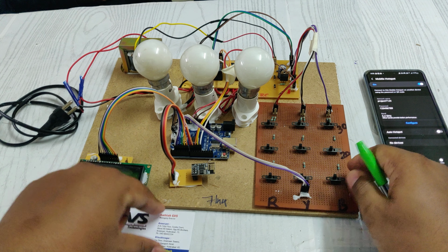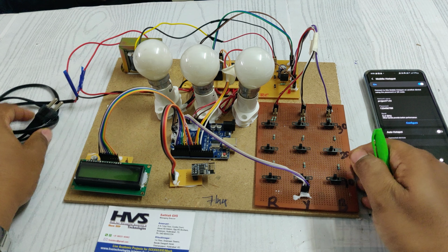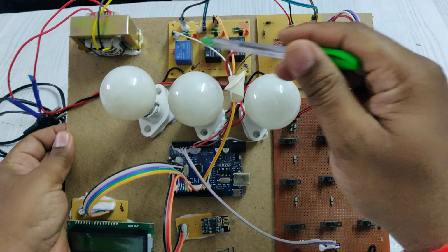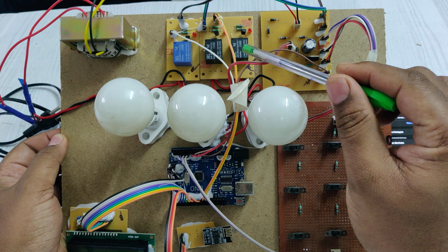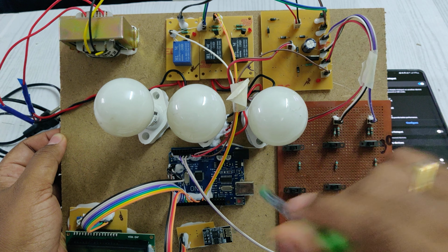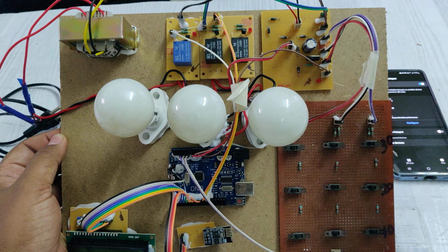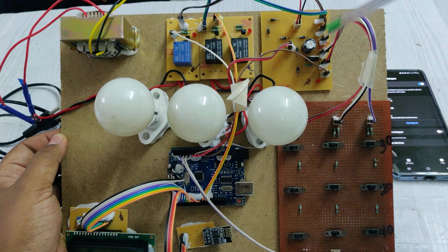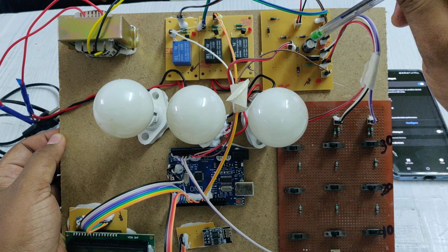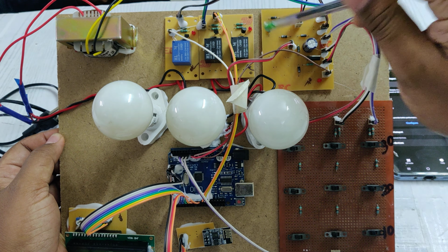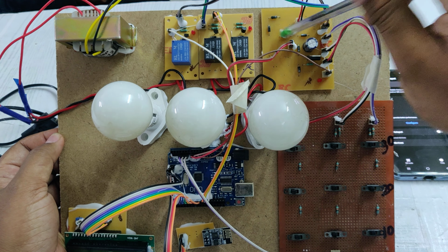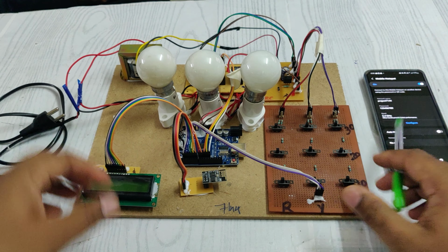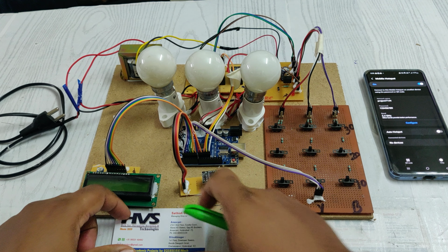In the whole system, the main power supply is getting 230 volts AC input, which is given in parallel as input to the 3 loads through these electromagnetic relays. These 3 relays act as switches, and the operating voltage of our microcontroller is 5 volts. To convert the 12 volts AC coming out from the transformer to 5 volts DC, we use this regulated power supply board, which has rectification, filtration and regulation. After these three stages we get the 5 volts DC output, which is the main operating voltage of our Arduino Uno board.